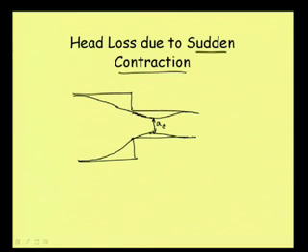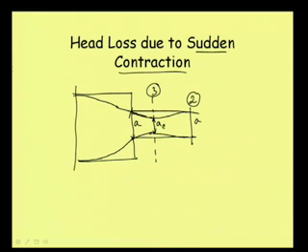So that we are getting here, and the diameter at this point, or say the area at this point, is A, and the area at this point or this point is the same. So this is the area A at this point. This is section 2, and this is an important section here, this is 3, and let this section be section 1. In fact, the loss is basically due to, not this contraction part, but this expansion part, that is, water expanding from here to here. That is the very basic reason for the head loss here.